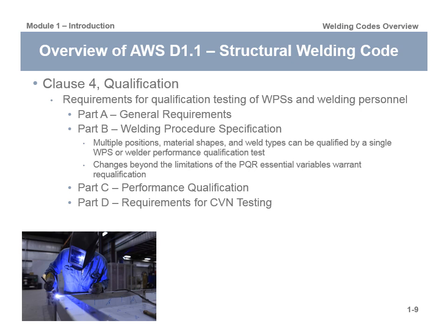A lot of people out there get Part B and Part C confused. They get welding procedure qualifications mixed up with people qualifications, welder qualifications. Two totally different categories, two totally different sports, however you want to classify it in your mind. Part B and Part C are totally different animals.